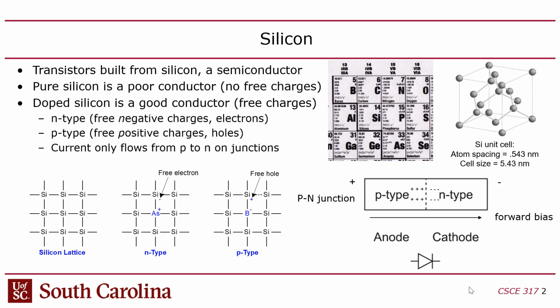So what ends up happening is the charge carriers move toward the junction, because this positive voltage attracts these electron charge carriers, right? And the negative voltage here is attracting the hole charge carriers, and the charge carriers kind of just meet up in the middle. And then that allows current to be conveyed from the P side to the N side.